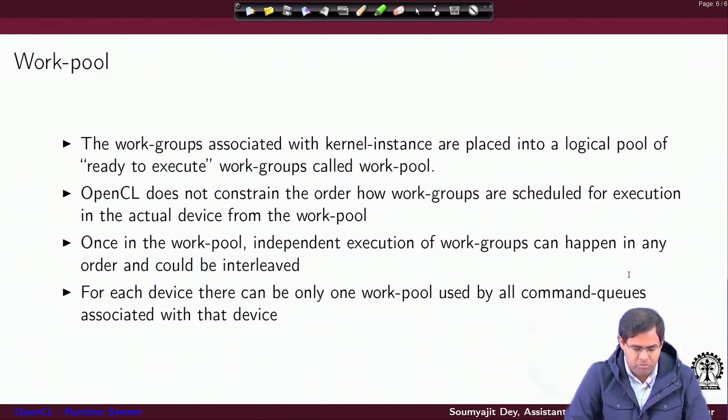Once in the work pool, you have independent execution of work groups which can happen in any order, and they can interleave among each other. Some work groups will execute up to some point, and then maybe they are waiting for some long latency operation to complete, and by that time some other work groups can be launched and executed, and so on and so forth.